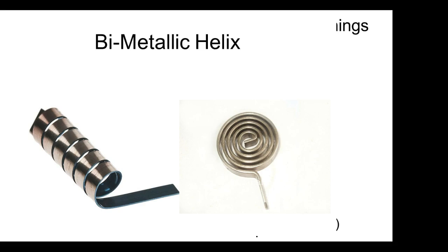They'll have a metal tube that actually senses. The helix, the spiral will be running down inside the system. You clamp it on one end, so what happens is that when it heats up, this thing is either going to turn clockwise or counterclockwise, depending on how the bimetallic strip is.